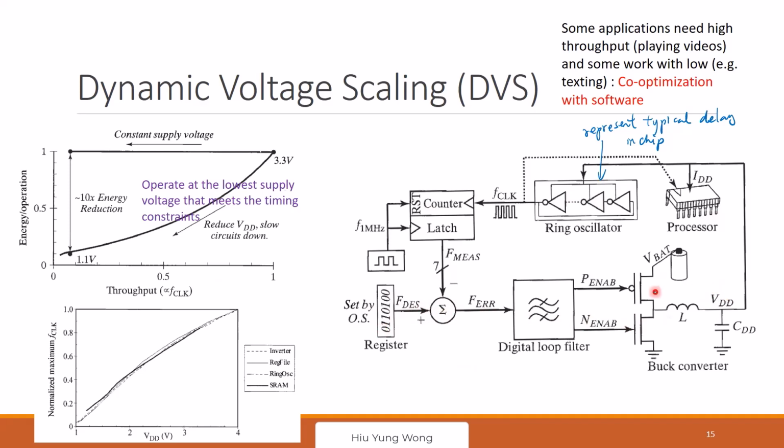But the main point here is that it's very common in any chip design. We will add a replica to detect what happens in other parts of the circuit, not just for the operating frequency but also for degradation, which is reflected in this ring oscillator too. Because as time goes by, your device will degrade, and its current will become smaller. We hope we can gauge how bad it is through this, and then do something from the operating system to keep it stable. Any questions regarding this topic?